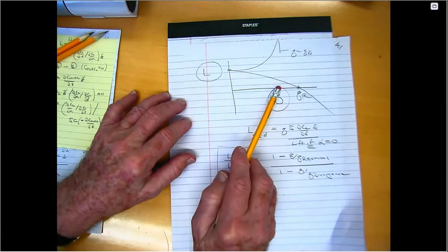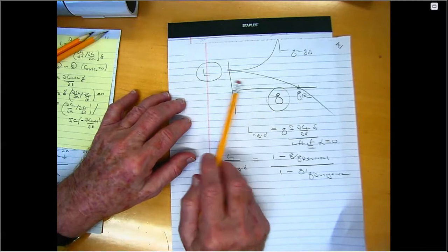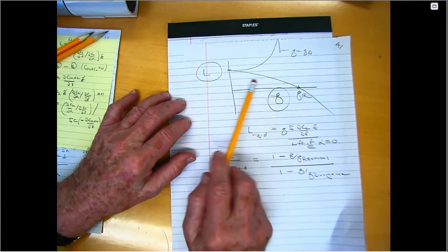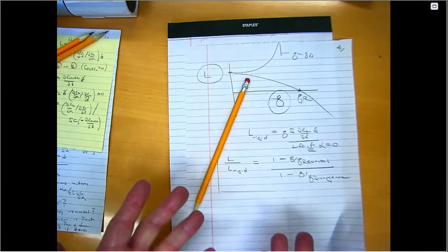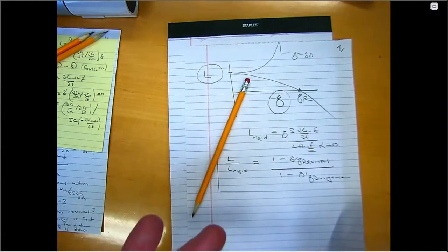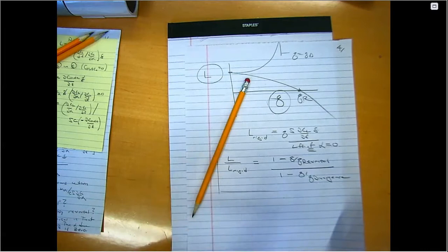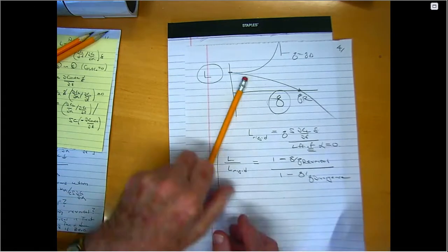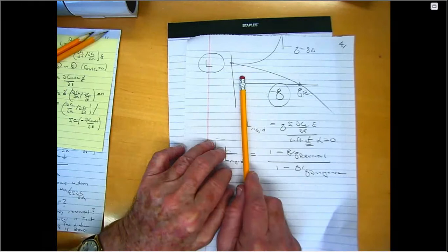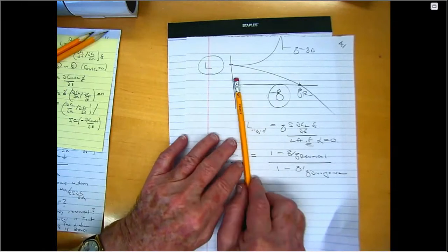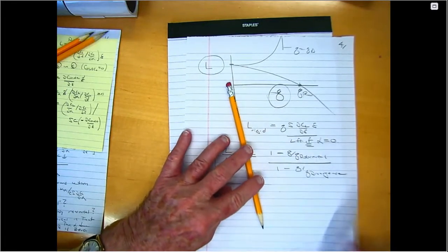if you ignore the flexibility of the wing, if you ignore aeroelastic effect. This is a static aeroelastic effect, right? The system has aerodynamic forces on it, and because of that, it's twisting. And because it's twisting, it's changing the aerodynamic forces. And the combination of that interaction is such that the lift is less than if you ignore the aerodynamic elastic interaction.